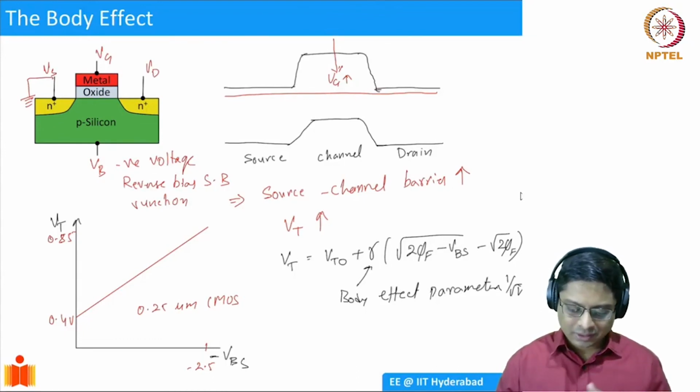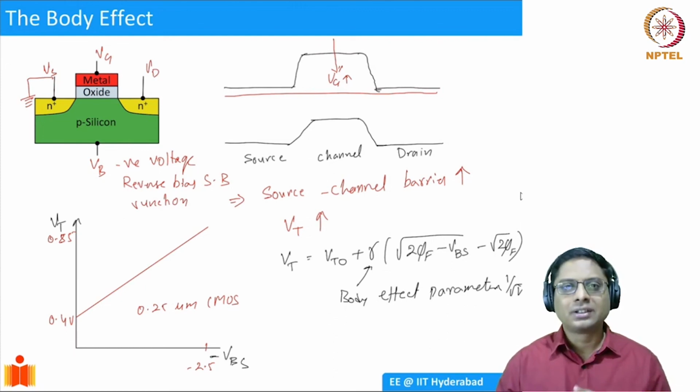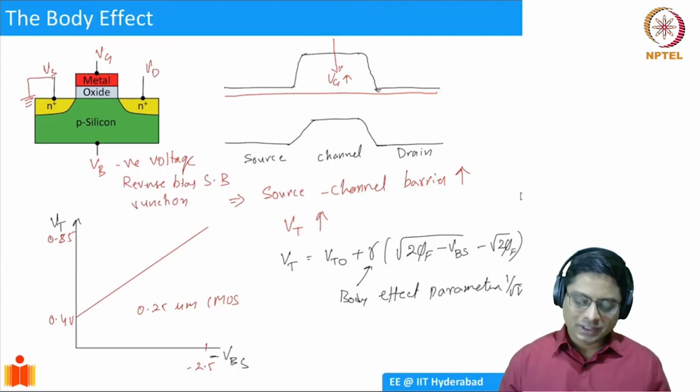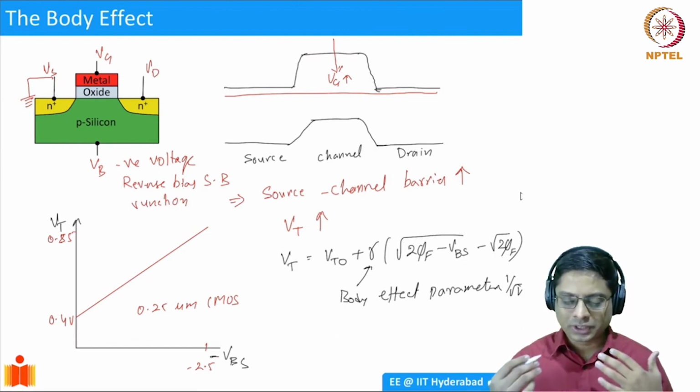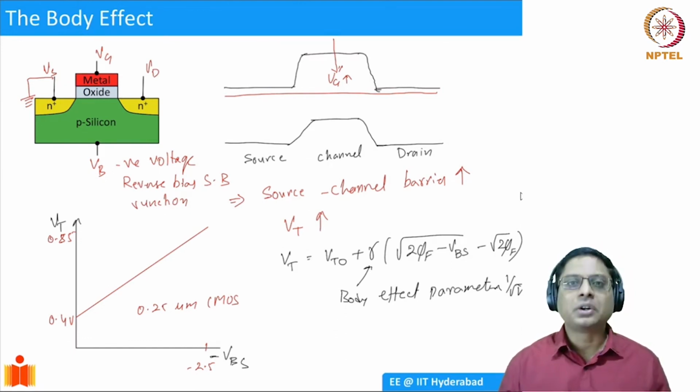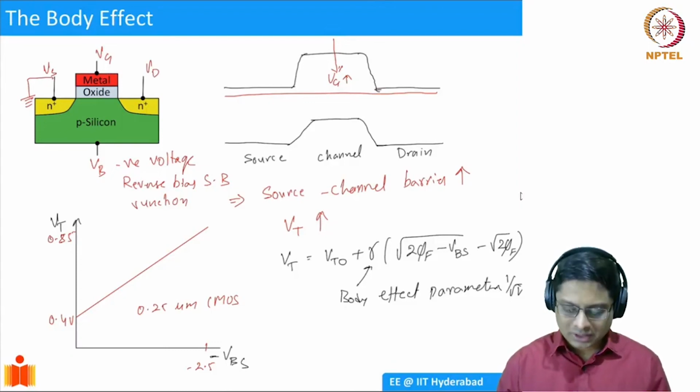So to summarize, the main tools that we have are, as a user, we can change the drain voltage, gate voltage, or the bulk voltage, all of them with respect to the source, and we can calculate. So if you have a body effect, well, the VT changes. If body voltage was 0, then you have VT naught, which is the default VT, or it can change depending on the body effect. Okay. So with that, I would like to stop this discussion here today.